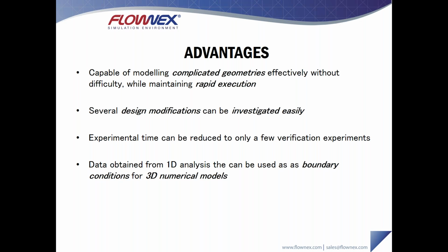So we can parameterize values, run parametric studies, and take a look at how varying parameters can change the response of our network or our system. I'll be covering that in the example I'll be going over. You'll get a first-hand look at how we can set up parameter tables within Flownex to vary things like engine operating conditions or even engine geometry.